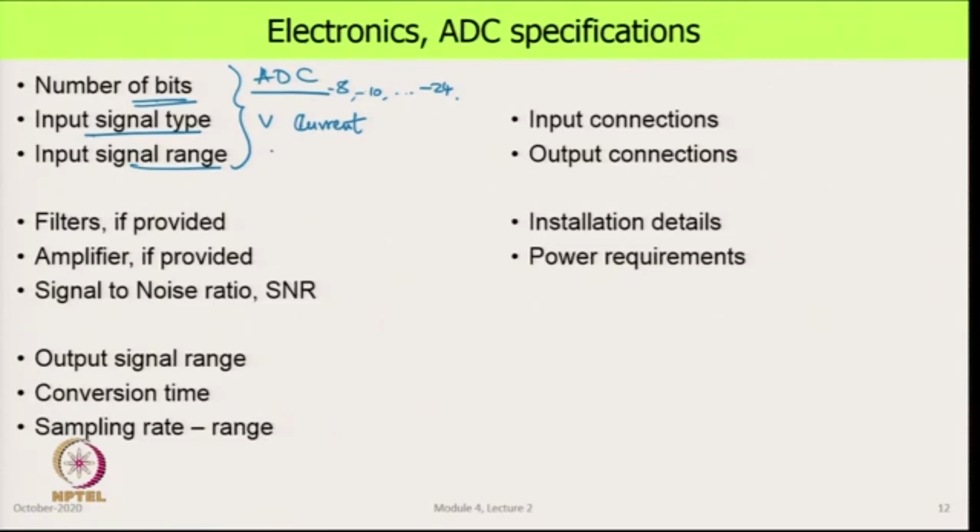The range tells you that at the input to this analog to digital converter, this signal, whether it is a voltage or a current, must be within this range. At the lowest value, the digital value will have all zeros. At the upper range, it will have all ones. We will see later on how this is very important in our uncertainty analysis. And also, when you are designing the experiment, why we have to understand this and select the correct type of A to D converter.